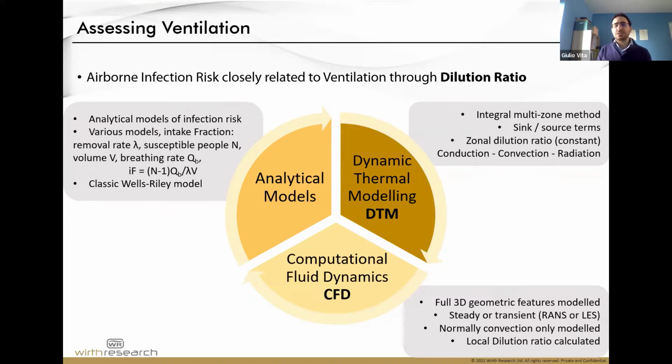CFD is the most complex one. It allows you to model all geometric features and obtain a local dilution ratio. So you can actually see within the same room how your local dilution ratio varies.